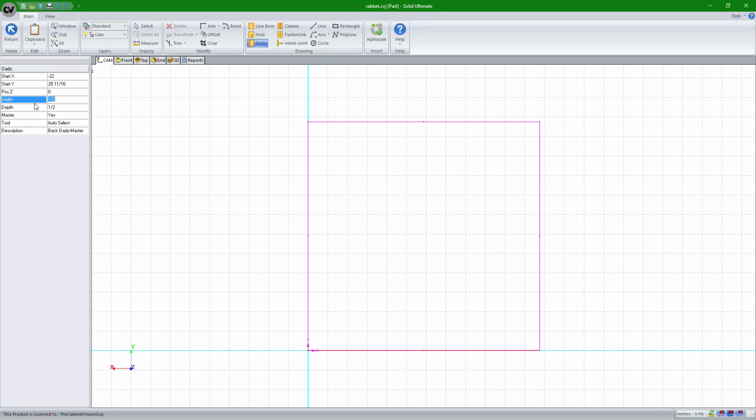1.5 inches. And a depth of, well, we want it a little bit thicker than half an inch, so what we're going to do is we will create it at 0.75. Now what that does is that the width of the rabbet right here from the edge to the inside of this part will be a half an inch wide, which the way I've got it set up is correct. If your rabbet is supposed to be less than that, you should adjust for whatever values you need. The depth, we want that to be the thickness of the material that we're using. So by default, we can just put 3/4 of an inch, and we can adjust that later on.